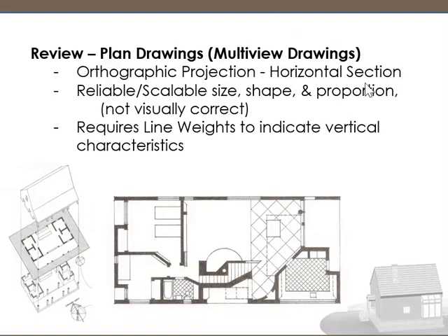So we know about multi-view drawings, right? The orthographic projection, you guys, we all worked on that. A multi-view drawing is taking a floor plan or plan drawing and horizontally cutting it around 4 feet. Remember, we did our floor plans and they're very scalable. Normally they're in 1/4 inch, right? And they require various line weights. We use the darkest line weights on the outside. And then as we work our way into a multi-view drawing, the things that are less prominent get lower line weights. We talked about this.